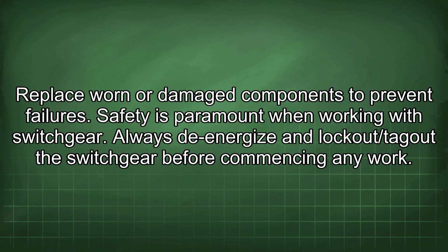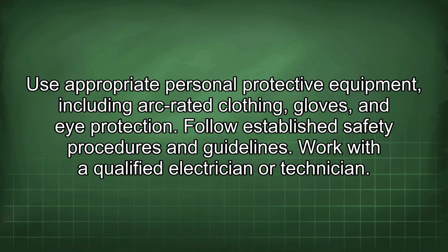Safety is paramount when working with switchgear. Always de-energize and lockout/tag out the switchgear before commencing any work. Use appropriate personal protective equipment, including ARC-rated clothing, gloves, and eye protection. Follow established safety procedures and guidelines. Work with a qualified electrician or technician.